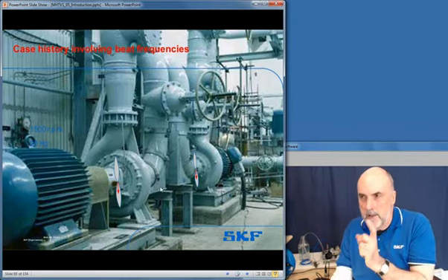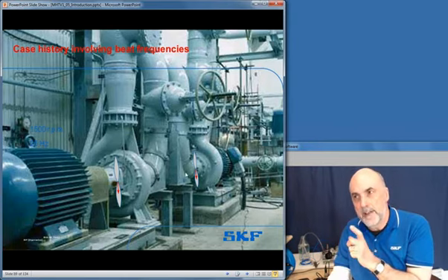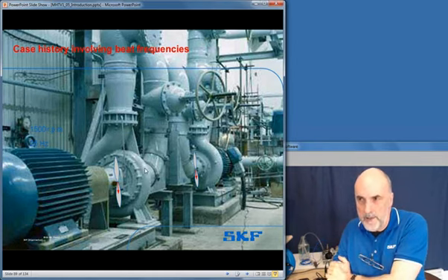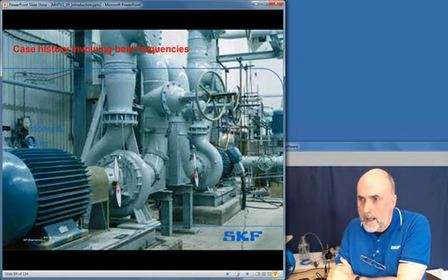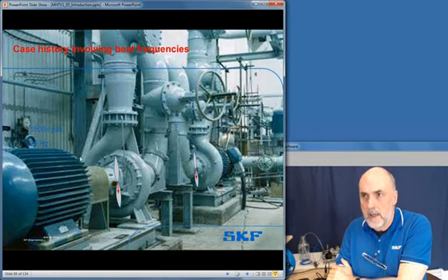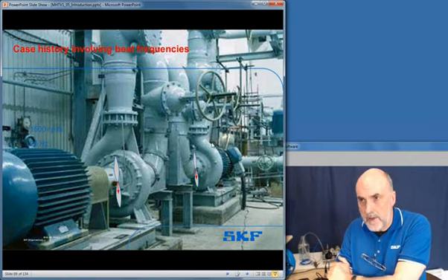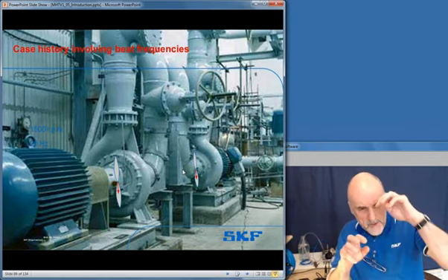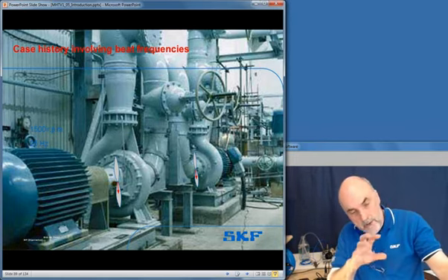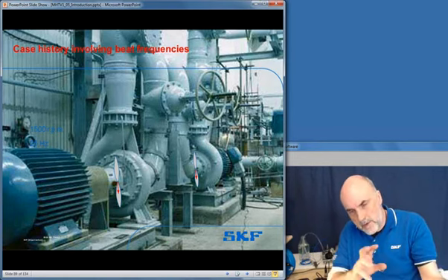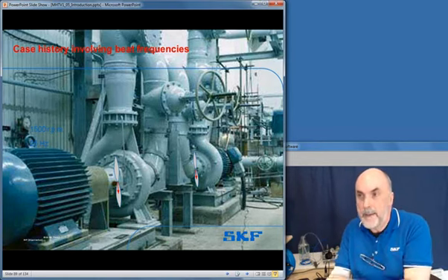These two slides are out of sequence, so I do apologise. Another example is a job we did some years ago, where the two machines were talking to each other. There were two machines, 1,500 revolutions per minute each, two bladed impellers, and there was a beat frequency. The two machines were interfering with each other and creating a beat frequency, and that beat frequency was something like 18 revolutions per minute. That was coinciding with the natural frequency of the structure and causing cracking.